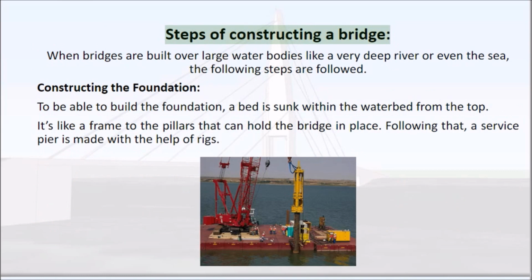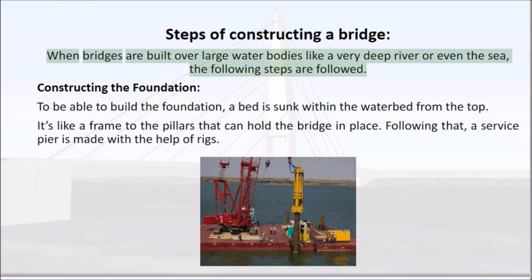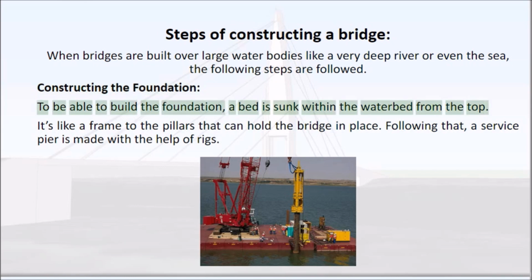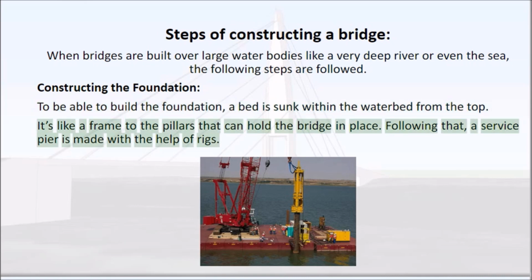Steps of constructing a bridge. When bridges are built over large water bodies like a very deep river or even the sea, the following steps are followed. Constructing the foundation. To be able to build the foundation, a bed is sunk within the waterbed from the top. It's like a frame for the pillars that can hold the bridge in place. Following that, a service pier is made with the help of rigs.